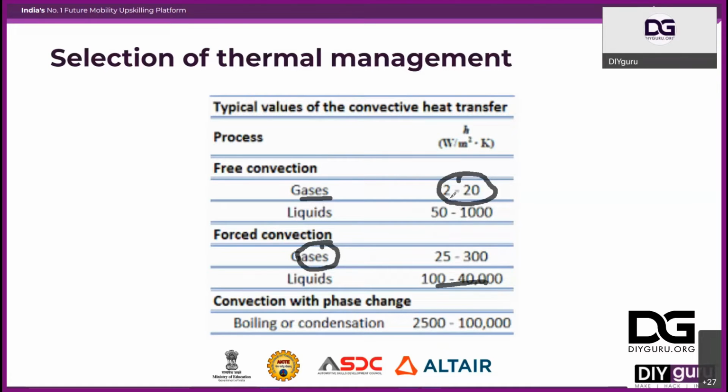If you want to cool something, you blow very hard on it. You don't just blow a little, very slowly. You try to blow hard, increasing the outlet velocity of your air, so that the thing gets cooled down. That's why this h value increases as the fluid velocity increases.